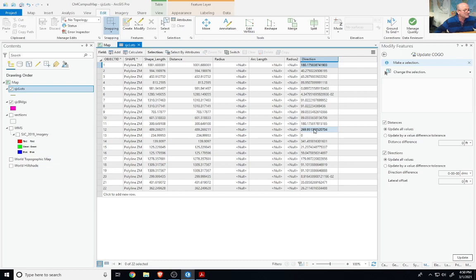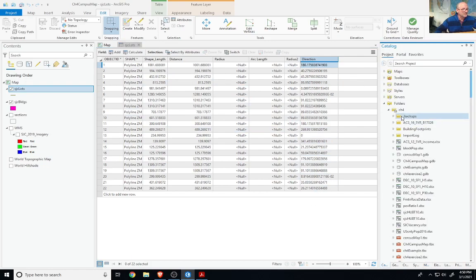We have one line that's 269 degrees, which is almost due west. So we don't have the correct direction. We can flip the lines around and do some things, but if this state doesn't want us to, then we don't. And we can actually do some more calculations on that to get the quadrant bearing actually working. But I don't think ArcGIS is working the way it should. I'm going to look into that a little bit further. But at this point, we're good to go. We can send this off to a shapefile and send that on to the client.